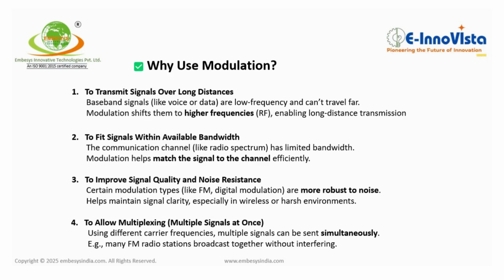Why use modulation? The need for modulation is to transmit signals over long distances. Baseband signals like voice or data are low frequency and can't travel far. Modulation shifts them to higher frequency, enabling long distance transmission. And to fit signals within available bandwidth, the communication channel like the radio spectrum has limited bandwidth, so modulation helps match the signal to the channel efficiently,